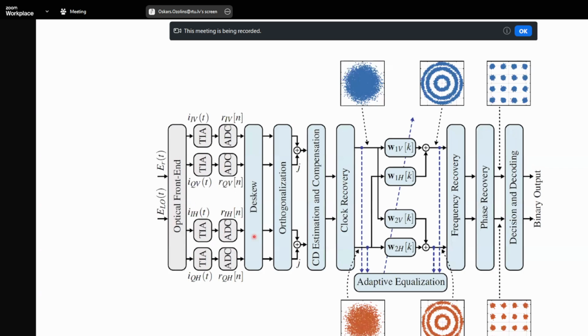In the experiments we do in research, we usually have an instrument here, and we collect signals at this place and record them as samples, with a trace for each of these electrical signals. So we have electrical voltage samples equidistantly spaced, and a number of those samples depending on the sampling rate and the memory we use in the oscilloscope.